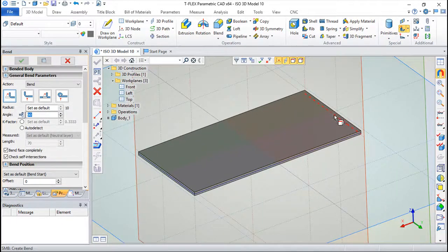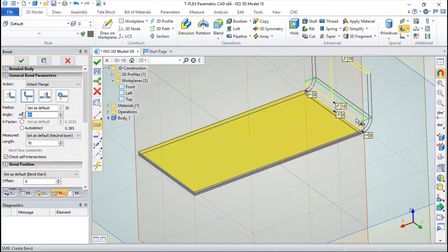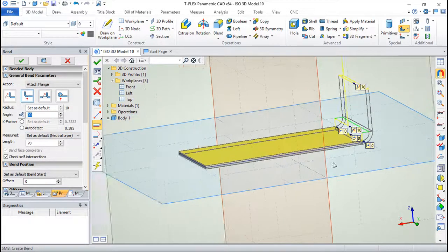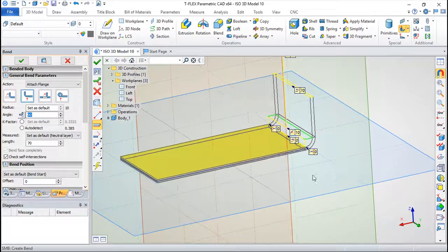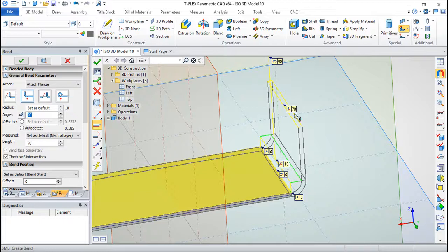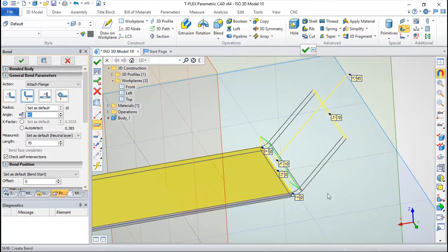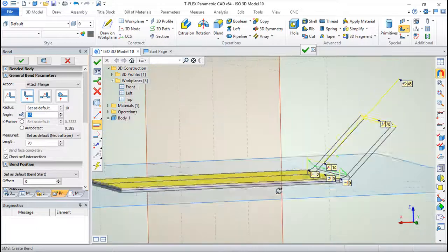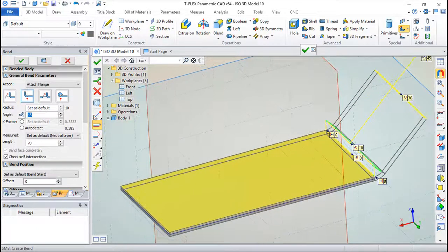The first thing I will create is to choose my edge, and by default already you grab these options here and insert them in my operation. I can change what I want, okay, the radius, the distance, the angles. For example, if I don't want 90 degrees, I want 45, so it will assume that. So everything is open to be defined.